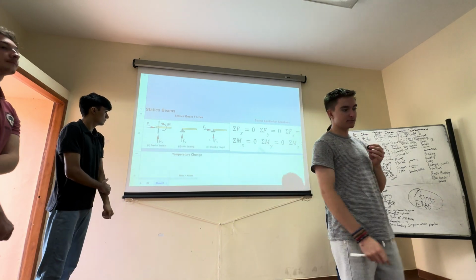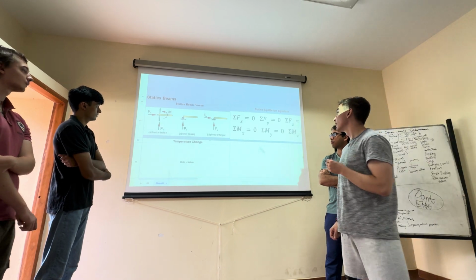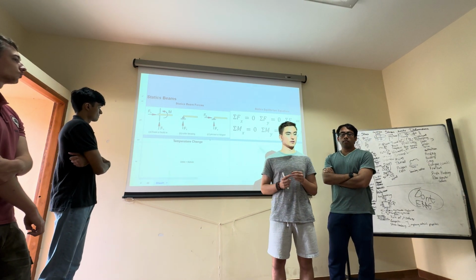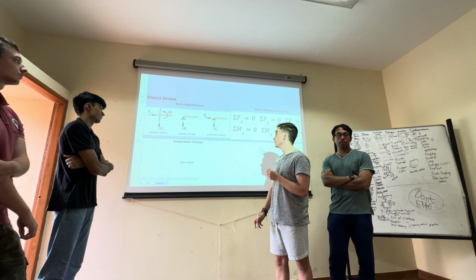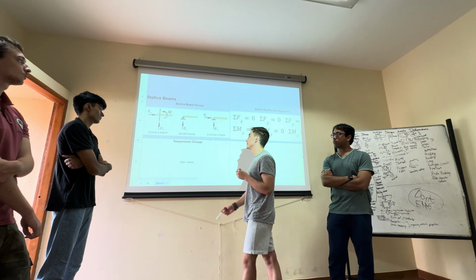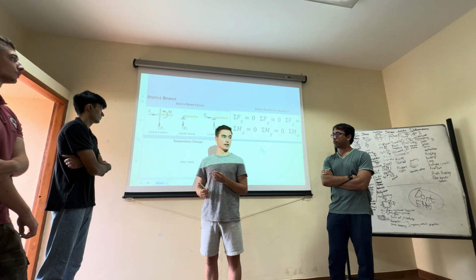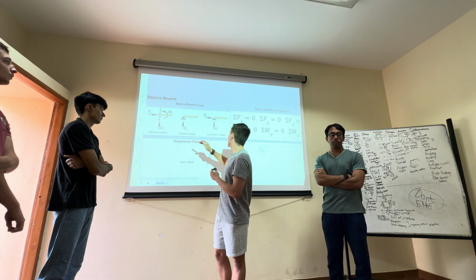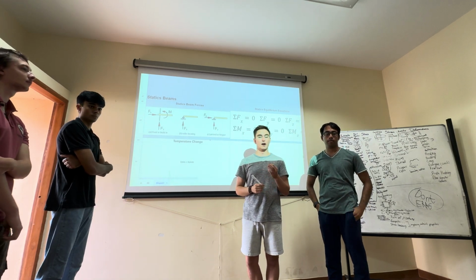And so going back to beams again, we wanted to include these generic statics problems of beam loading and beam moments for the core forces, also extending that to the equilibrium equations. And so the three generic beam supports you see are the fixed, whether it's attached to a wall, which is usually how you illustrate it, or any other way that could be fixed, the roller, and then the pin or hinge. Of course these are all going to act differently and have different forces and moments.